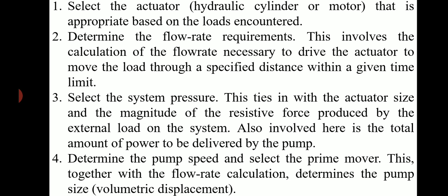First one, select the actuator, hydraulic cylinder or motor, that is appropriate based on the loads encountered. Second one, determine the flow rate requirements. This involves the calculation of the flow rate necessary to drive the actuator to move the load through a specified distance within a given time limit.